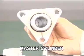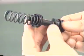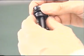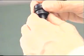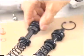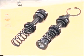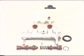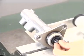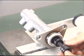Inspect the master cylinder bore for scoring or corrosion. Inspect the piston and cups for wear, scoring, cracks, or swelling. If any of these need replacement, use the parts from the cylinder kit. Apply lithium soap-based glycol grease to rubber parts shown here. Assemble the parts to the master cylinder following the reverse procedures.